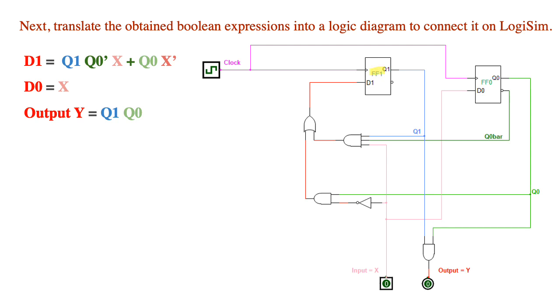We labeled them F1 and F0, but remember to connect the clocks of the flip-flops together, just one clock. Make sure the frequency of the clock is not too fast so we can be comfortable inputting the sequence bits serially at our own pace, so you can even observe the output being updated to 1.